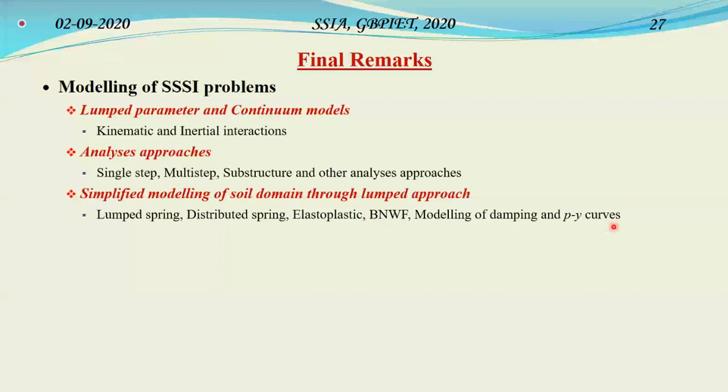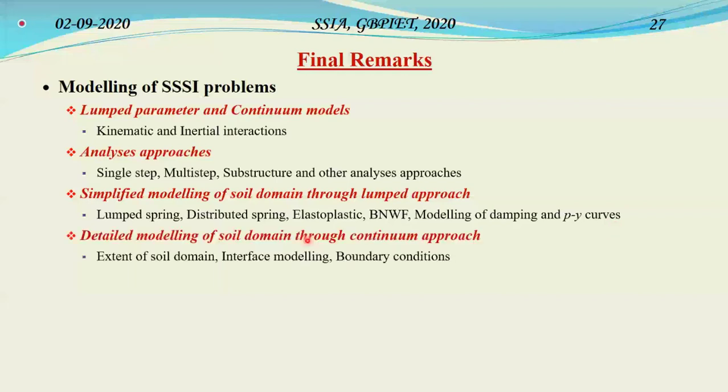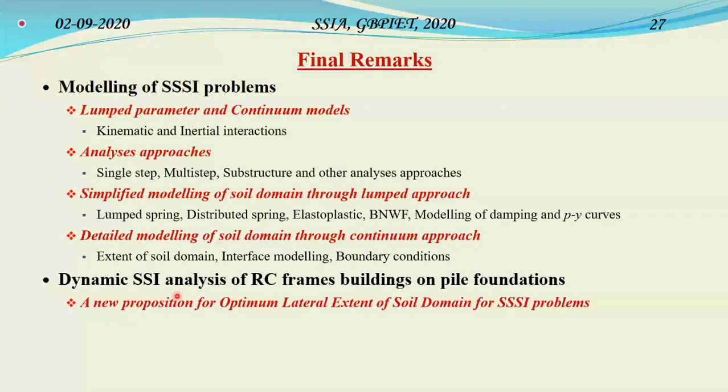and we have shown a little bit about the modeling of damping and PY curves. We also talked a little bit about the detailed modeling of the soil domain through a continuum-based approach, where we mentioned the three most important aspects: extent of soil domain, interface modeling, and boundary conditions. And based on this understanding, I presented to you a small work done from our side about dynamic SSI analysis of RC frame buildings on pile foundation, where we proposed a new method of giving optimum lateral extent of soil domain for SSI problems involving RC frames.